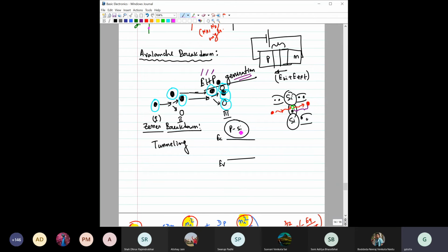Okay. So Fermi energy level is nothing, you can think of it like that. For P type, the Fermi energy level would be very close to this EV, like this is EF, right? Now please do not ask about more details about the Fermi level, but just take it this way: for P type the Fermi level is very close to the valence band, and for N type silicon the Fermi level would be very close to that of this EC.